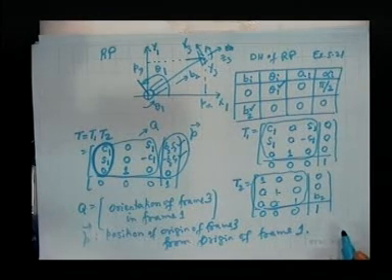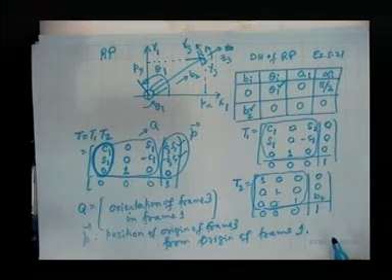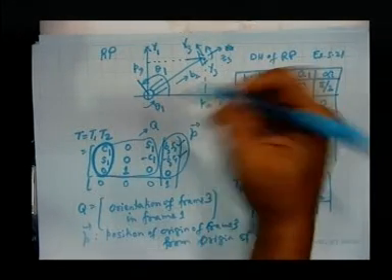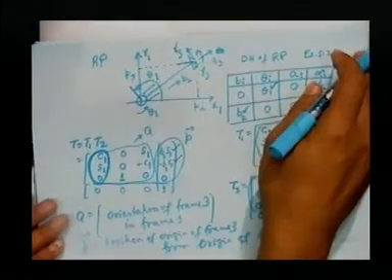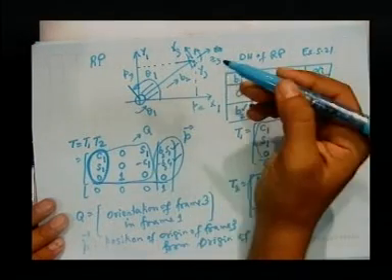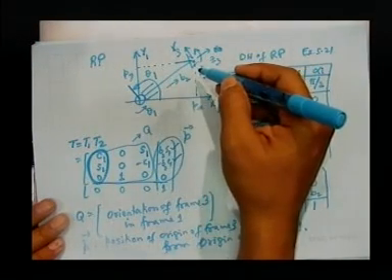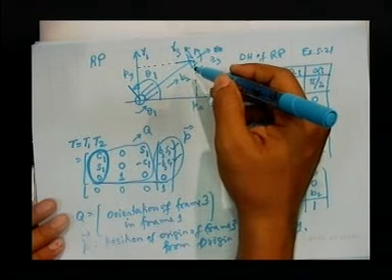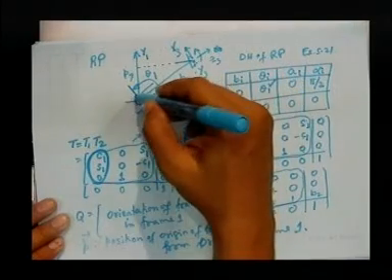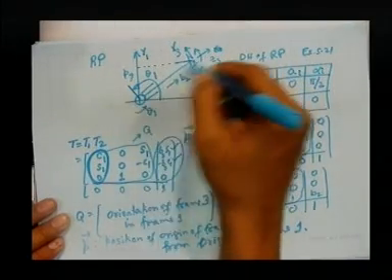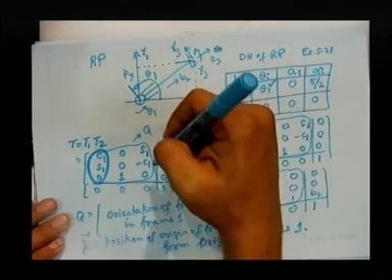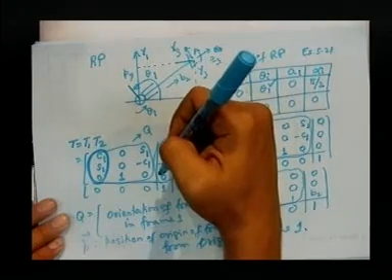By the way, sometimes you may get lost: why are we doing so many calculations? What is our purpose? Please do not forget your purpose. The purpose is, if I am moving the robot using its joints by providing some angles, where is the robot going? I need to know, because later on I will have to control it, so that if there is a certain object it should not hit, it should not go there. So, I need to know for certain angular motion, certain translational motion, where the end effector is going, and that process we are doing is called forward kinematics.